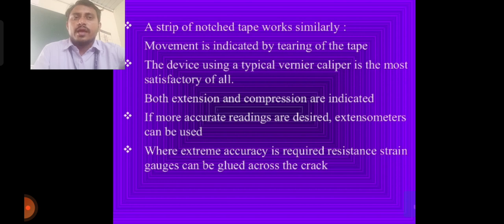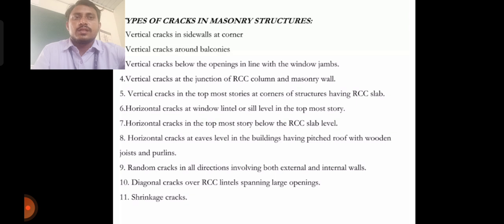If more accurate readings are desired, extensometers can be used. Where extreme accuracy is required, resistance strain gauges can be glued across the crack.